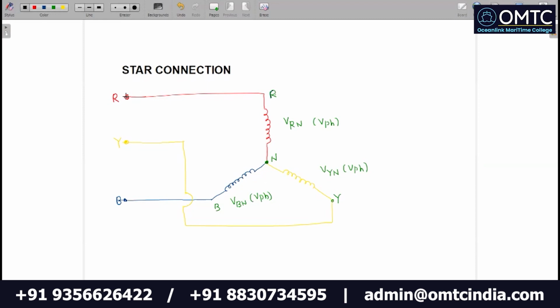But look at this. This is a red line and this is a yellow line. The voltage between red line and yellow line is called a line voltage. We can name it as VRY. It is a voltage between line to line, red line and yellow line. Similarly, there is a voltage between yellow line and blue line, that is also a line voltage. Similarly, there is a voltage between blue line and red line, that is also a line voltage. Line voltage means line to line voltage.